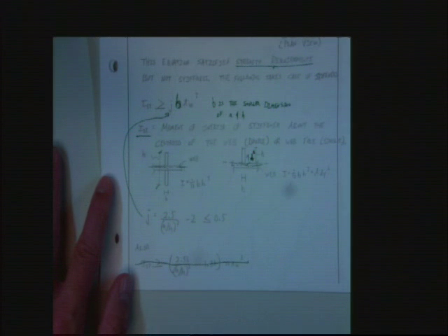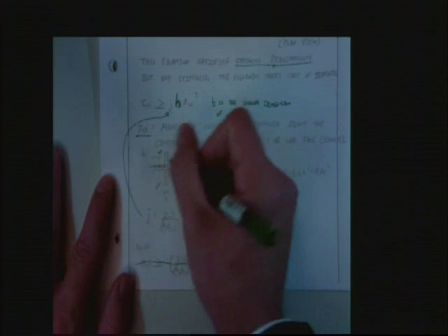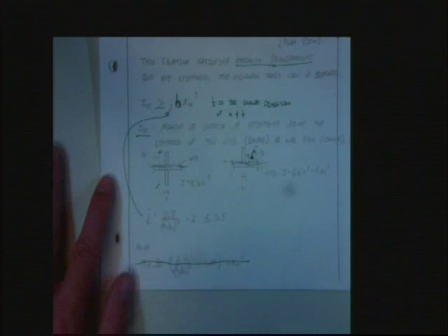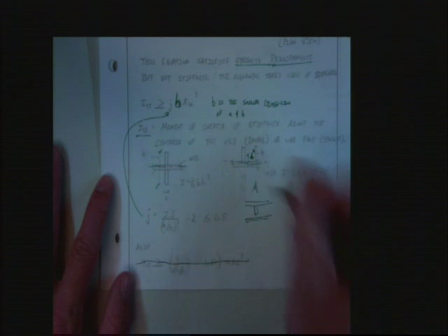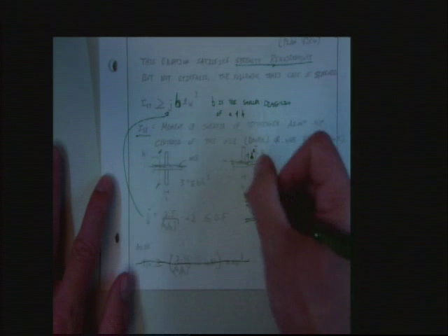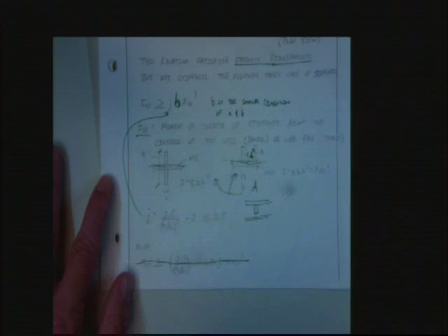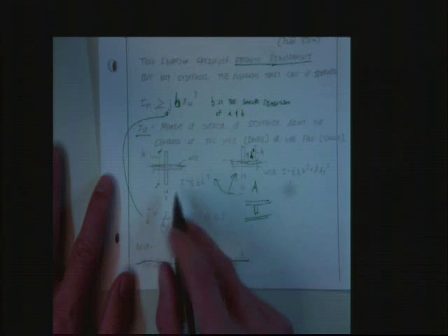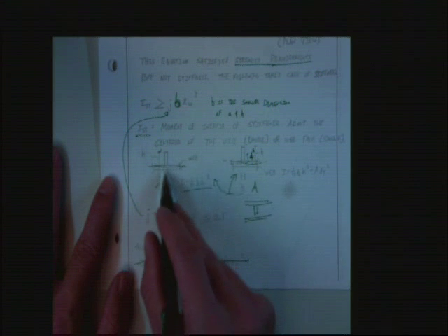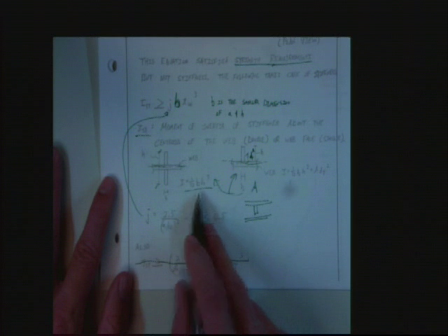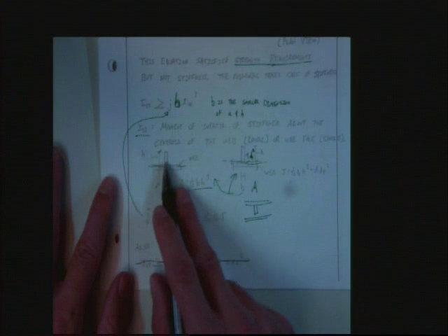And this is just a little weird, but what you do is you imagine this is a plan view looking down. So if I had a girder here, and it had a stiffener in it, and my eye was above, looking down on it, it would see one of these two things. It's looking down, and what you're going to do is find the moment of inertia of the stiffener about the web. It's just 1/12 BH cubed, where B is the width of the stiffener, H is the height of the stiffener.